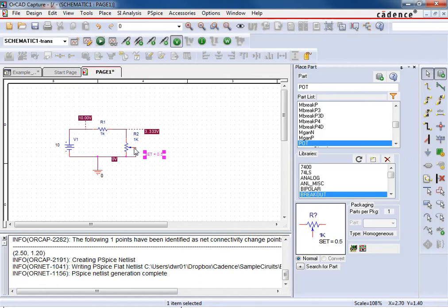Now you have to be careful. Sometimes, depending on how you short these together, when we go to different ones here, we'll show you in a second what I mean. And so basically it's just a 500 ohm resistor, 1 kilo ohm. Simple voltage division would say that's a third of your power supply. So that's why it's 3.33 volts.